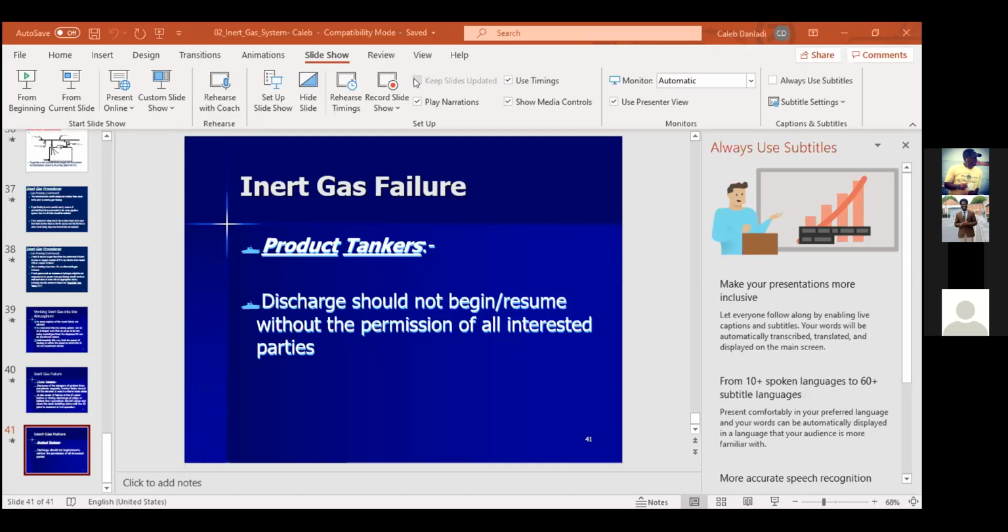Any further questions, please? I think in addition to that, Captain Sobajo, in Abu Dhabi and Dubai, when a ship is going alongside, there are barges that supply inert gas to the ship. So when you want to start, it can supply you instead of from the boiler. You have an uptake of inert gas from around the poop deck, or if you know where the power supply is, just by the pen locker, around the pen locker access, you still have one there.